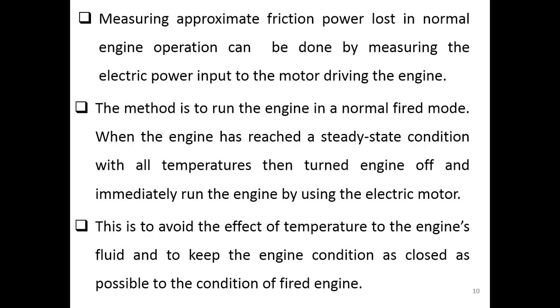So we run the engine under normal operations, and then we turn off the engine, and suddenly we turn on our electric motor and use this electric motor to run the engine. Then we measure the electric power that we supply to the electric motor and use this amount of electric power to indicate the amount of the friction power.